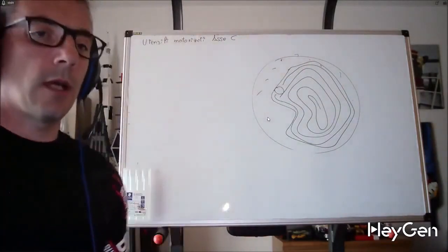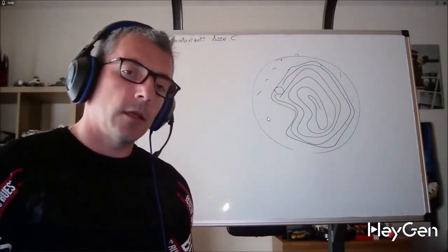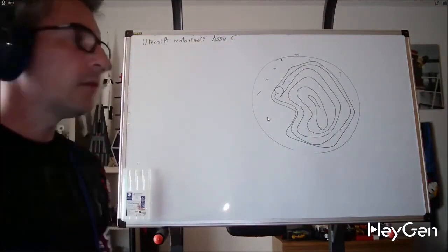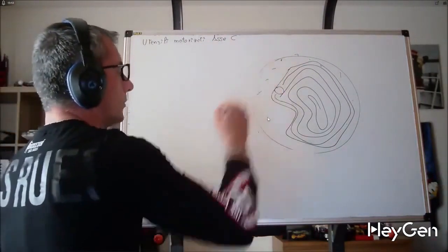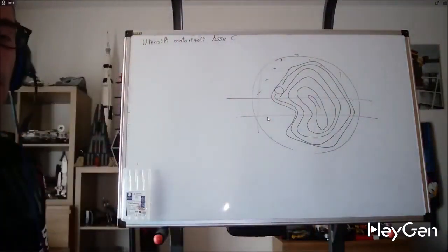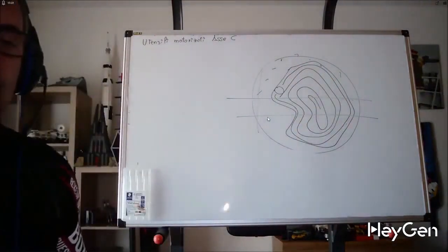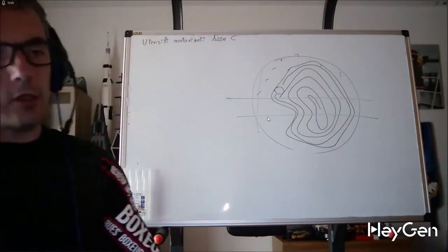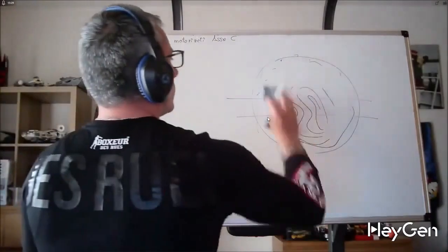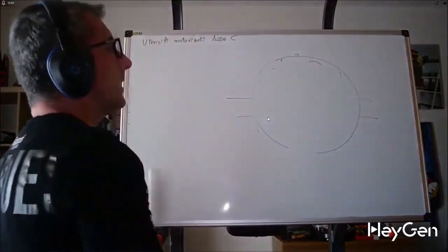So, the limitation of ISO programming when it comes to powered tools is the difficulty in managing complex profiles. As long as we're just making a hole, a notch, or a central notch, there aren't any major issues. But when we start thinking about pockets, it gets a bit trickier, and that's where I prefer to use conversational programming. If we have a lathe with a C-axis at the front of the piece, we can do whatever we want radially.